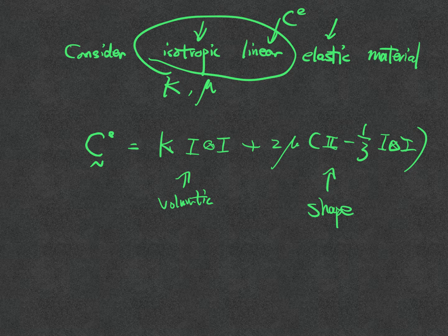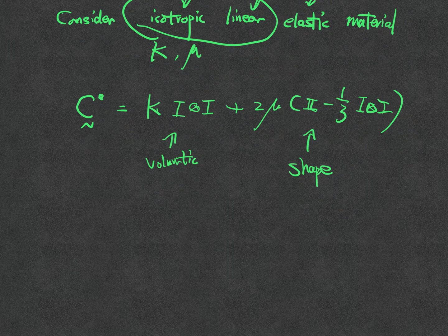And for isotropic material, a very important characteristic is that if I change the shape, the material just changes shape, it won't change the size. If I change the size, if the material is isotropic, I won't change the shape, it will just change the size. Now, in real life, the material is anisotropic, so if I apply the isotropic compaction there, I may change the shape a little bit. The circle may become an ellipsoid. Then there would be an additional coupling term between the first and the second term, but here we don't have that, okay?